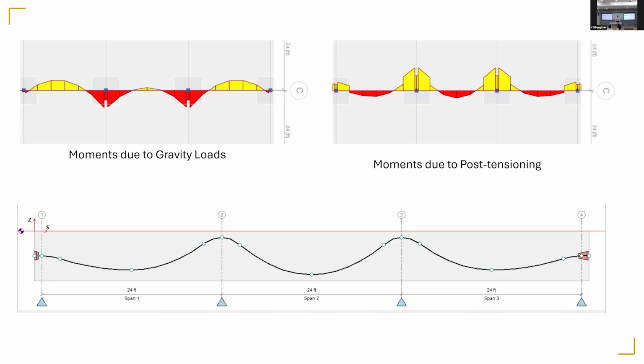That's why almost all tall buildings now invariably use post-tensioned flat slabs, because they are flat, they are easy to construct, they don't have deflection, and so on. And then you can have longer spans, up to 9-10 meters is possible without beams.